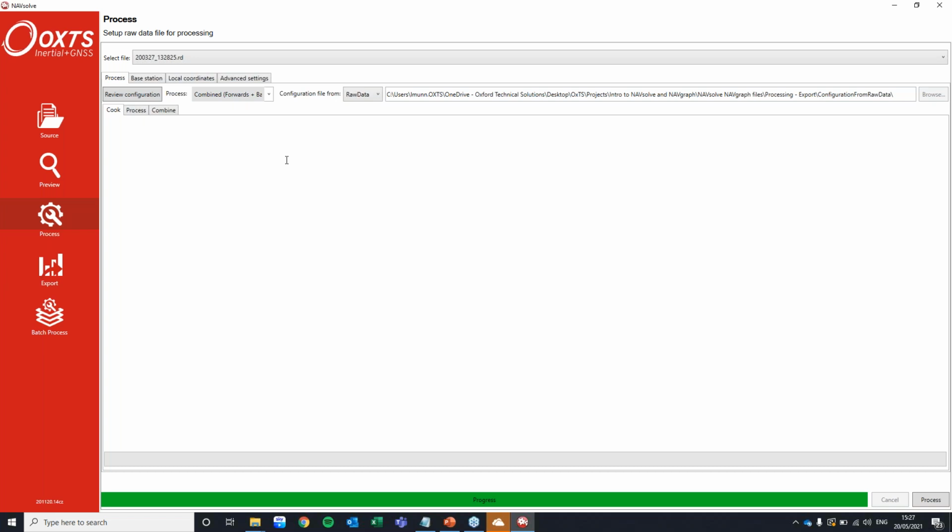So if you're going through a tunnel, you'll go through the tunnel and then there'll be a little patch after the tunnel where you're receiving GPS signal, but you don't have position lock. When you do combined, you'll have position lock from the other direction until you lose that signal again. So it can improve in post-process the GPS position and therefore the position accuracy.